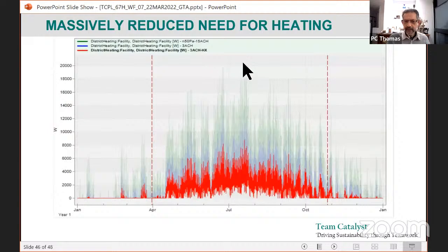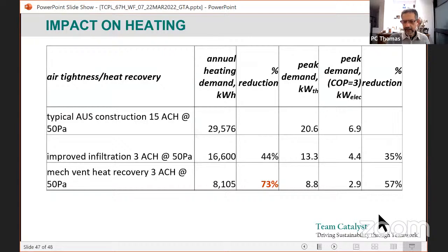So from there in the beginning till down here. And if I put that into a spreadsheet, I can say that I can reduce 3/4 of the heating energy required, and I can reduce the size of the heating system by half. Okay, so these are interesting things that you can work out by doing this sort of simulation.